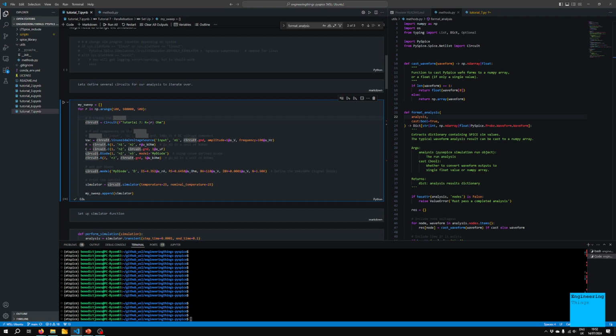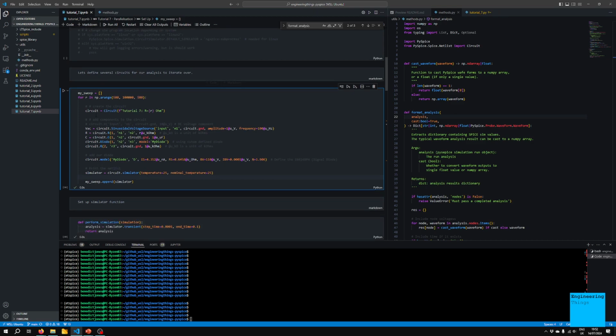And what I'm going to do is loop through the resistor values used in this circuit, and I'm going to actually create several circuits, or actually tens and tens of circuits. And then what I want to do is execute all of them at the same time using multiprocessing. So if we were to do that normally, we'd probably either loop through and run each of these circuits independently, or in this case I actually create a sweep.